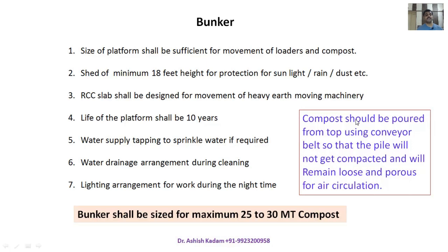Again, I am saying it here that even 1 gram of compost should get oxygen, should get air. That is what the planning should be. You have to design in such a way that every gram of the compost of this 25 to 30 metric ton of material which you are shifting into the bunker area should get sufficient air flow. That level of micro planning has to be there. That is the reason it should be very loose material. It should be like a sponge.